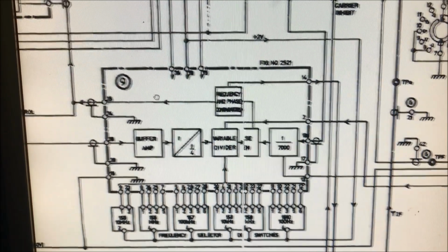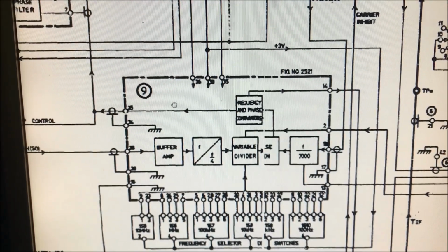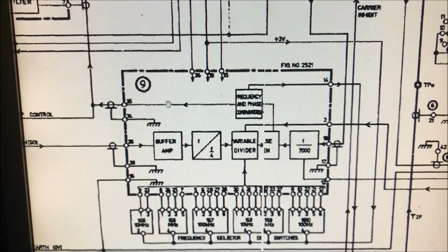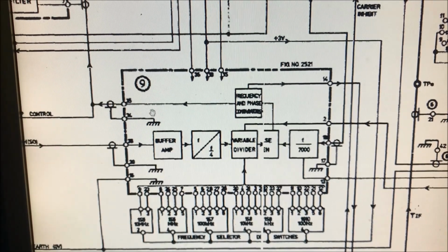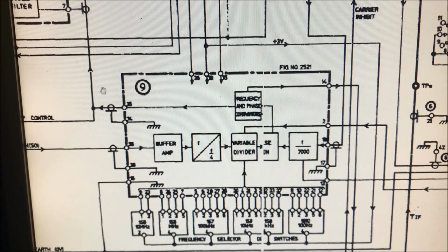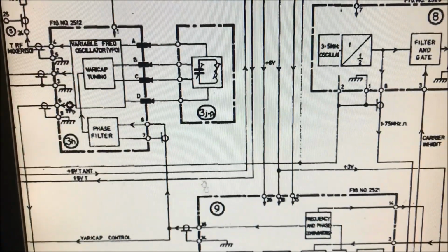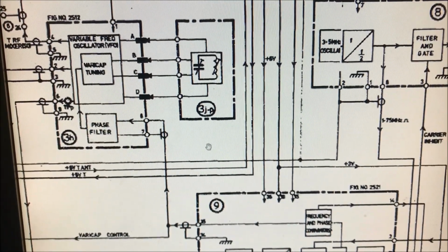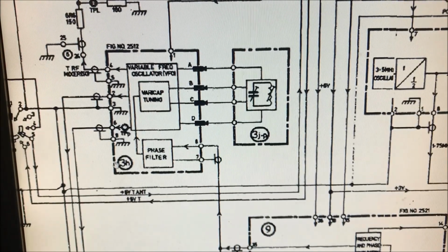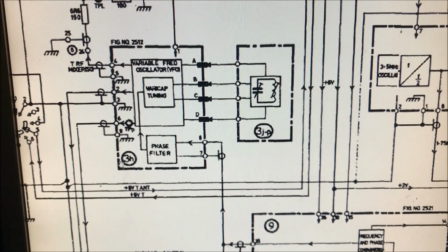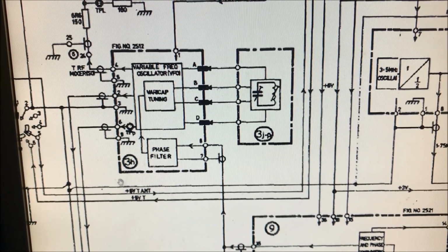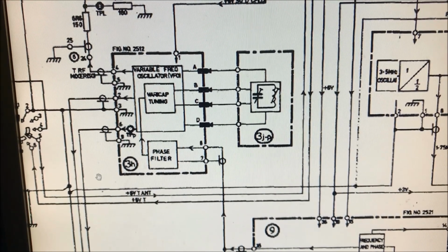What the synthesizer does with that is it's got a choice of sending any voltage between about 5 and 85, and depending on the frequency that we select, it sends that voltage up to the 3H board, and the 3H board is situated on the turret of the 320.